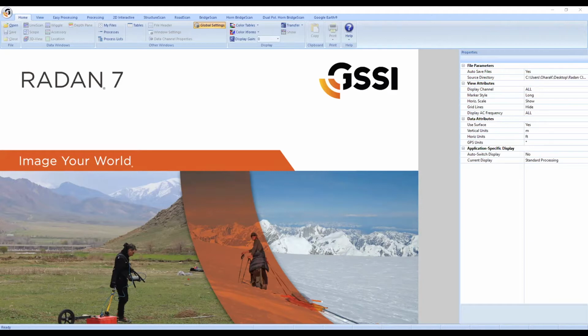It's pretty cool, and it allows you to get a more precise position for your targets. As we saw with 3D free draw, when we were double clicking on the edges of each target, where you double click, it does latch to the highest amplitude it can find. But when you double click and attach the other end of it, you might be missing some of the variability in depth as that target goes from one end of the grid to the other. So 2D interactive can allow you to get a more exact position, and it's also the tool to use when you're drawing in layers or changes in material.